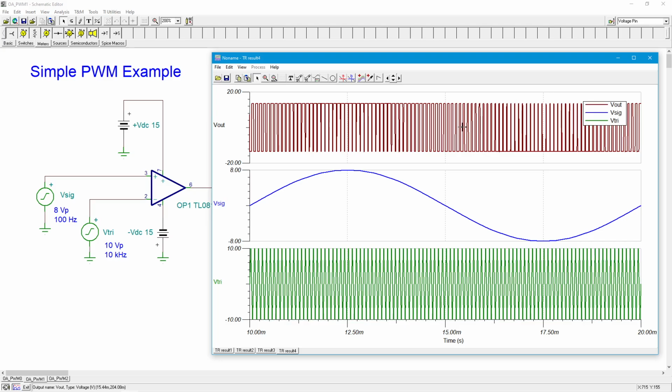But mathematically, the sine wave is in here, along with a whole bunch of other harmonics, just like when you take apart a plain ordinary 50% duty cycle square wave, it's a whole series of odd harmonics at a very specific ratio of amplitudes. You put in 1 kilohertz, you get the 1 kilohertz out, that's the fundamental, but you also get some 3 kilohertz, some 5, some 7, and so on. It just keeps on going forever. That makes up the signal.